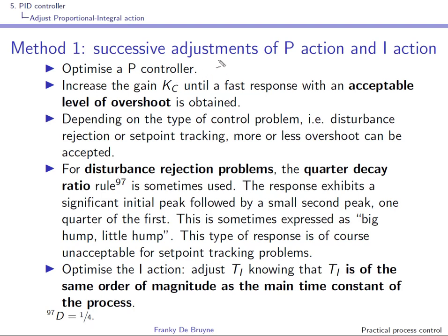We'll make the assumption here that PV is on set point when you do the set point change, and that you have deactivated the integral action. Often this is done by setting Ti equal to 0, although this might change with the vendor that has implemented the PI controller.